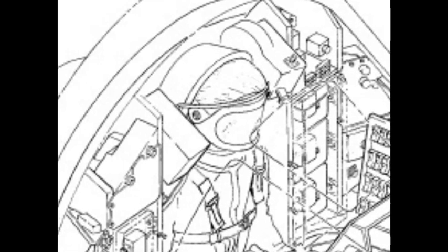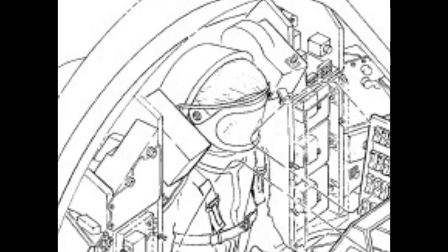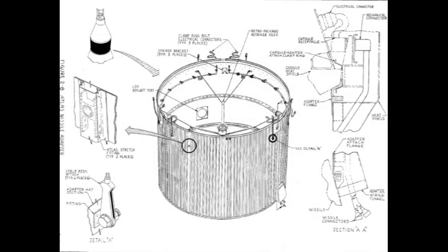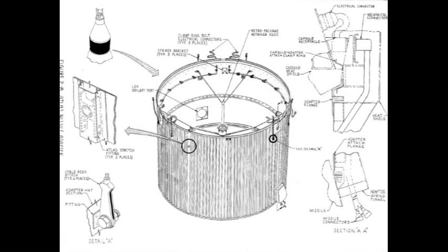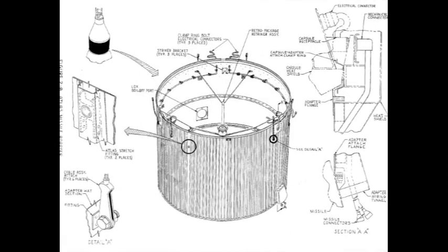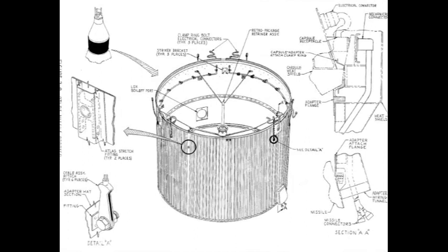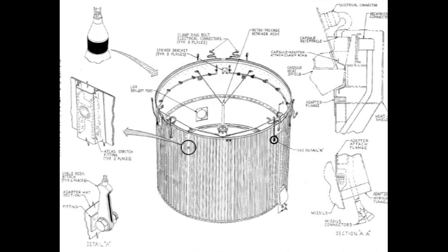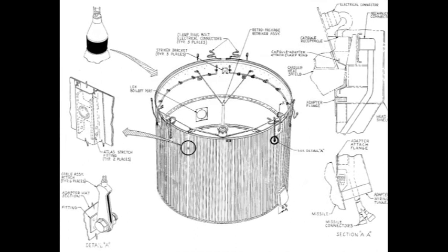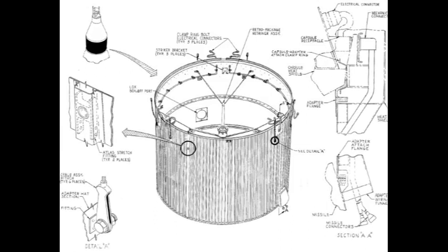The capsule is attached to the adapter by installing a chevron-shaped, segmented clamp ring over the mated flanges of the capsule forebody fiberglass attach ring and the adapter upper ring. 217. Atlas Missile Adapter. The Atlas Missile Adapter, figure 2.8, is a slightly tapered, cylindrical-shaped structure that is designed to mate the capsule with the Atlas missile.